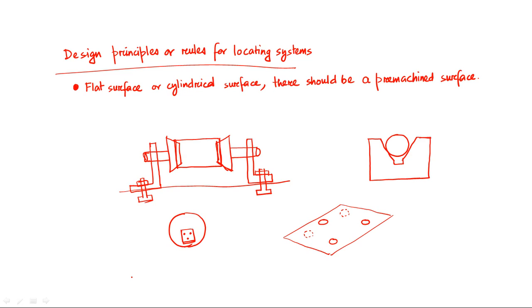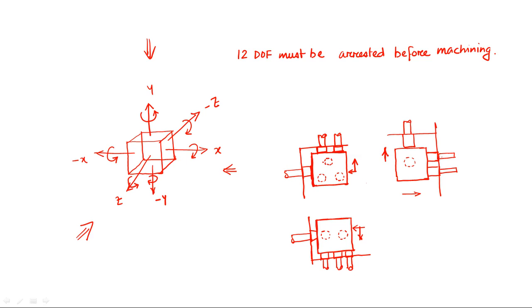Basically, in the locating pin, locating means, for any type of job, suppose this one, what will be the distance of the job from these 2 walls? That is also the location of the job. So to get that location, the location of the pins will basically decide the location of the job. So we should use the pins accurately, so that the location of the job will be accurate, and the function or further processes of the workpiece can be done smoothly.